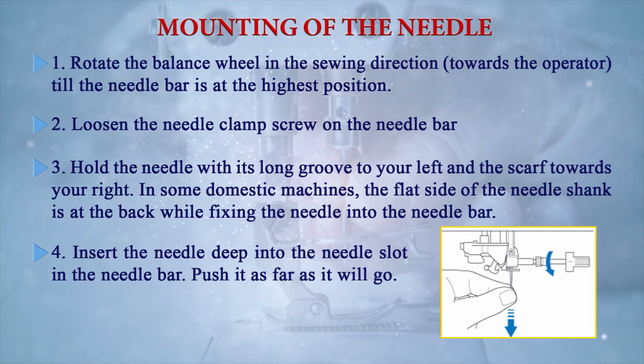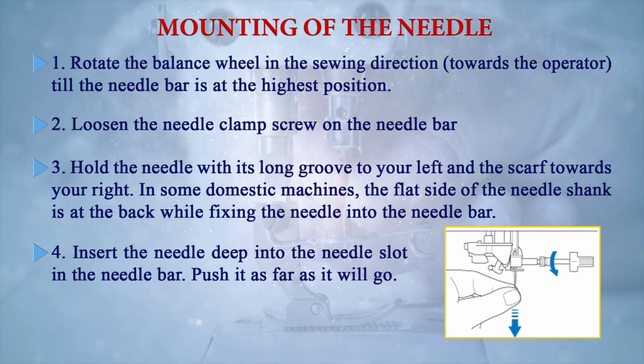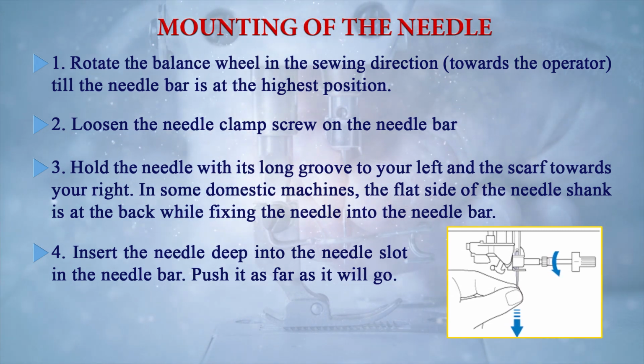So when you put the needle in the needle bar, just push it upward until it stops and then tighten the needle clamp screw. So this is the process of how we insert the needle in the needle bar. Now we have inserted the needle.